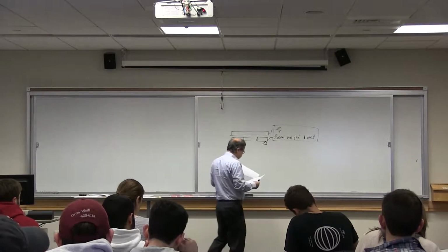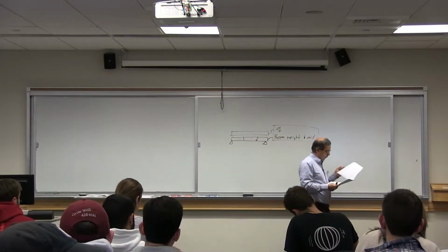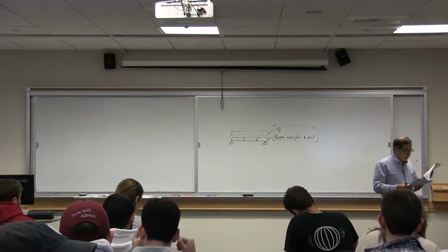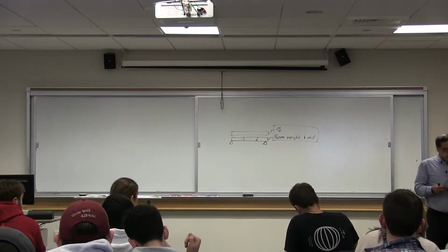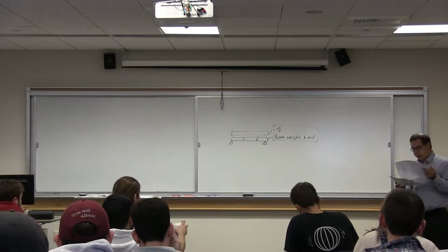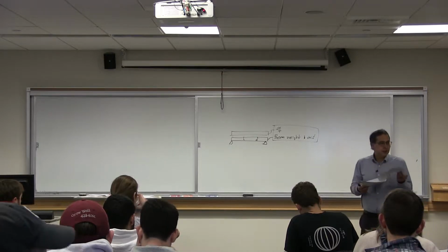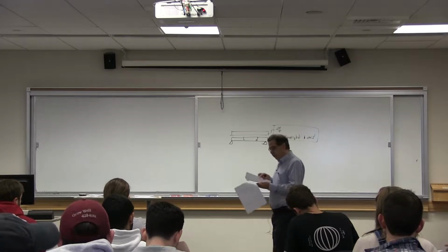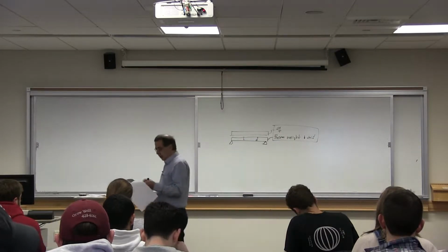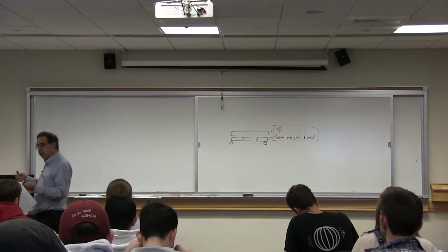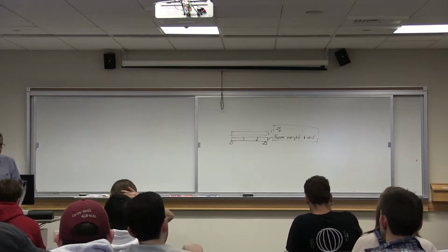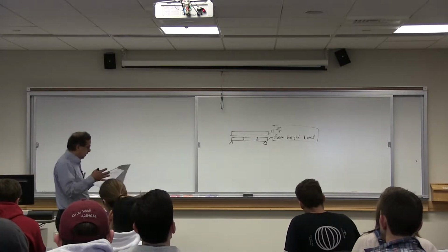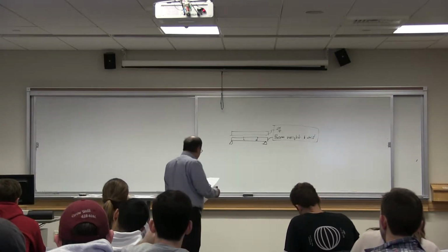So problem 2.6, the geometry is given obviously. It just says the unit weight that you want to consider is 150 pounds per cubic foot. So you can easily calculate. And this 150 pounds per cubic foot, as you can see, says reinforced concrete weight. That means consideration of the concrete as well as the reinforcement.